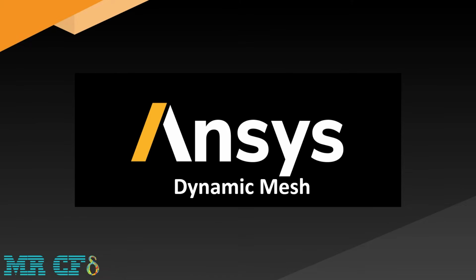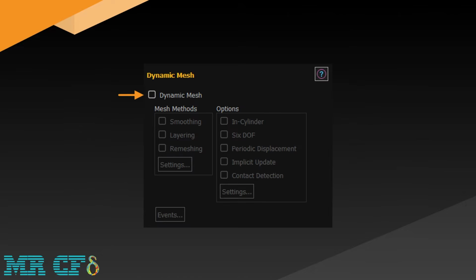By now, you've got a big picture of what dynamic mesh module is or where to use it. In the following, we intend to provide comprehensive information about the dynamic mesh module in ANSYS Fluent software. So first of all, we must activate the dynamic mesh module so that the settings related to the definition of the dynamic mesh are activated in the workspace.